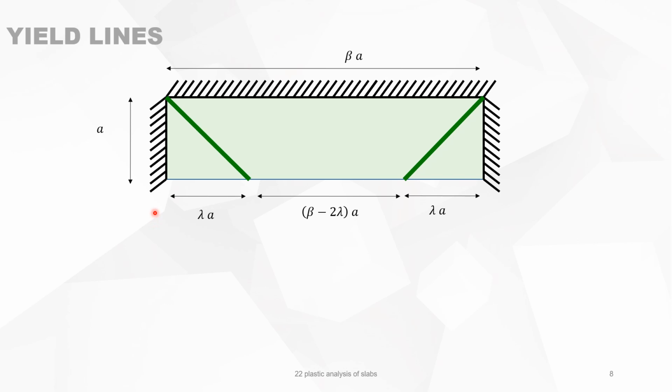And we will demonstrate here that you can look up the right position of the yield lines by maximizing the formula for the bending moment, just like we've done in the slides before. We will do it now for a balcony like this, but instead of the angle alpha, I will use lambda A, but that's the same. It's just another way of making it arithmetically. So the conditions, of course, are that lambda is smaller than 1 and beta is bigger than 2.